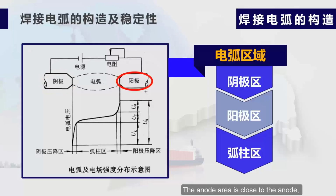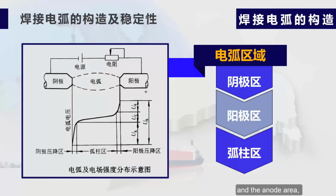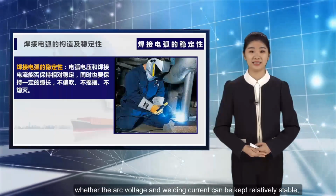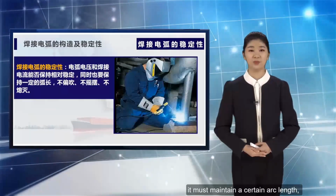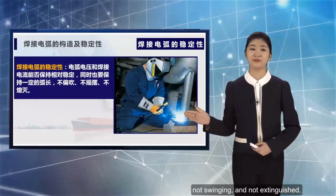The anode area is close to the anode, and the arc column area is a section between the cathode area and the anode area, and its length is much larger than that of the cathode area and the anode area, accounting for most of the arc length. The stability of the welding arc refers to whether the arc voltage and welding current can be kept relatively stable, and at the same time, it must maintain a certain arc length, not blowing, not swinging, and not extinguished.